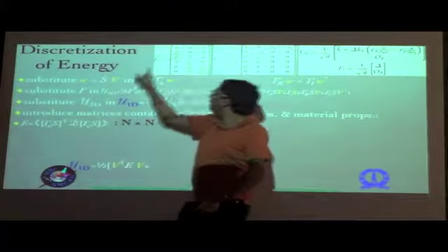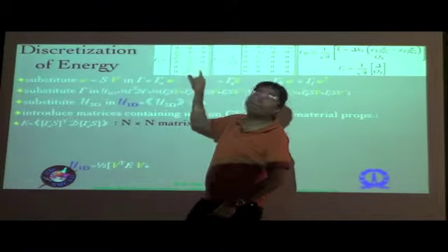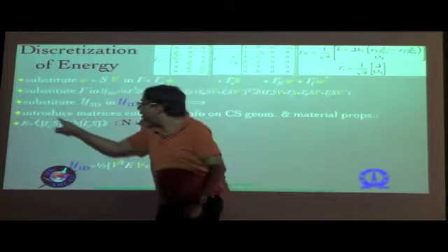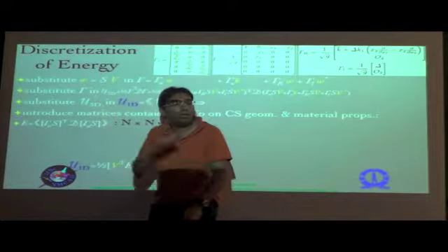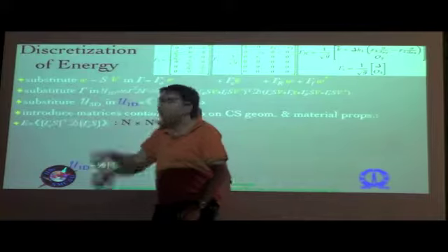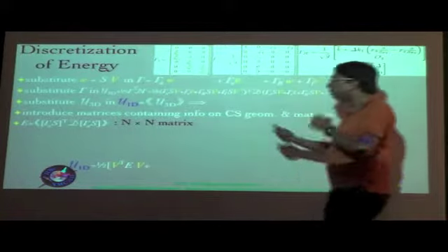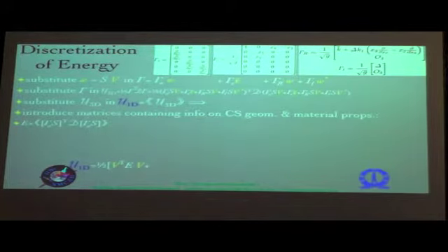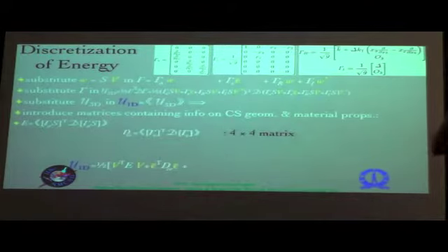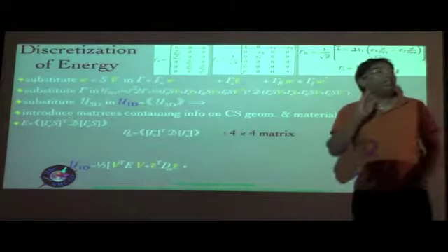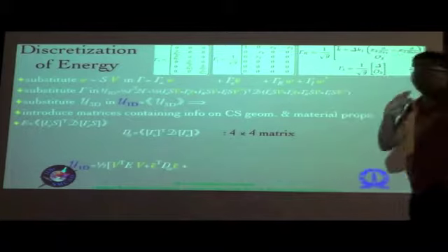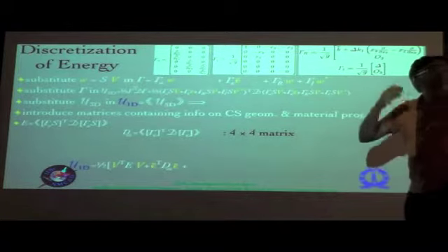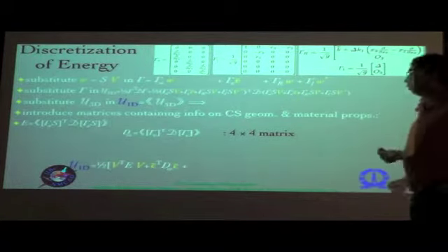So you're basically taking derivatives of that with respect to x2, x3 over here, and that's basically what you're doing here. And then of course multiplying by the material matrix and itself, and integrating over the cross section after multiplying by root G. So in other words, it also contains information about the initial twists and curvature as well, apart from the cross-sectional material distribution, material properties, and the geometry.